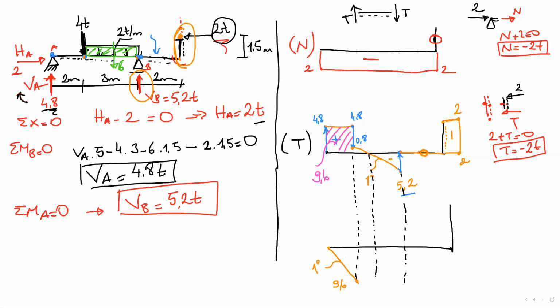Here is first degree. Now, by the way, let me show you this critical point. Here there is a zero shear force. So please be careful with this point. We need to calculate the location of this maximum and its magnitude.